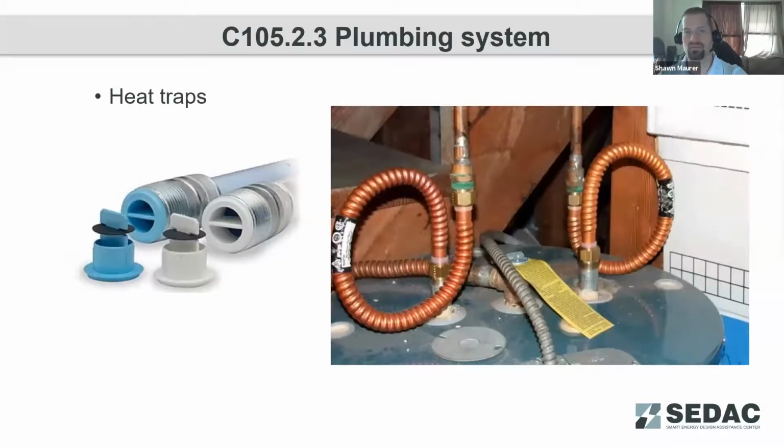The next thing to be aware of is heat traps. When you're looking at plumbing systems, you don't want hot water siphoning out of your hot water storage tank into the distribution system to the cold line or the hot water line, as that will result in significant energy losses. So these storage tanks on both commercial and residential systems are required to have heat traps in them to prevent that kind of hot water buoyancy, causing siphoning of hot water out of that storage tank and energy loss.